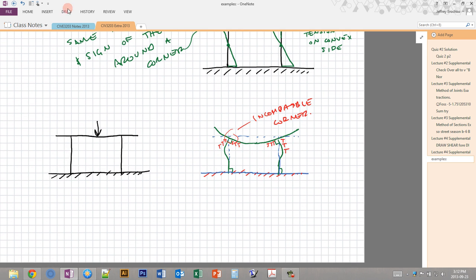Okay, so we've got to take another crack at this and see if we can do a better job. Let's draw the approximate shape before the load first. Here, let's draw it in red this time. So this time let's start with the corners. I think it's reasonable that this should be closing, right? Because this has to come back to 90. So that this is closing makes sense. Let's draw that on the other side too, because we have to end up back here. And this definitely has to twist out somehow, so this corner here has to also be closing for that to be compatible. And then to join these in the middle, we can draw something that looks like this. And then this goes straight out the end because there's no load on that.